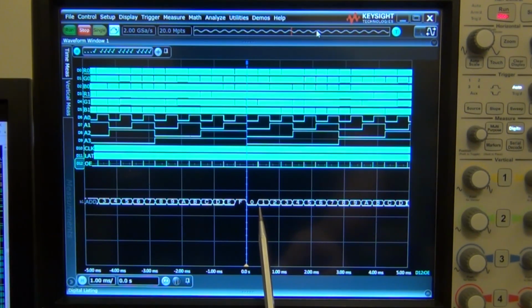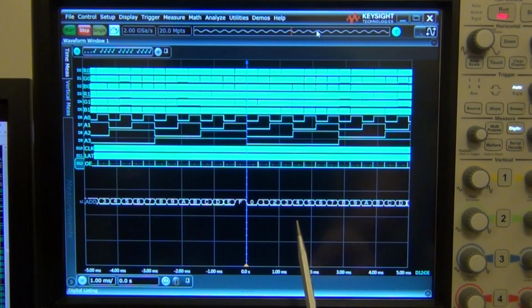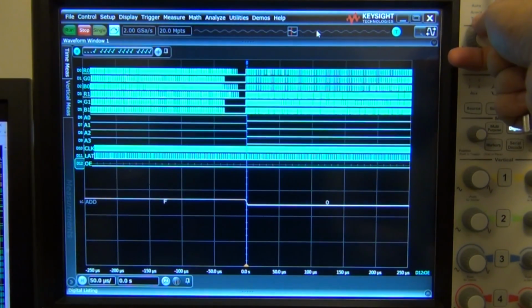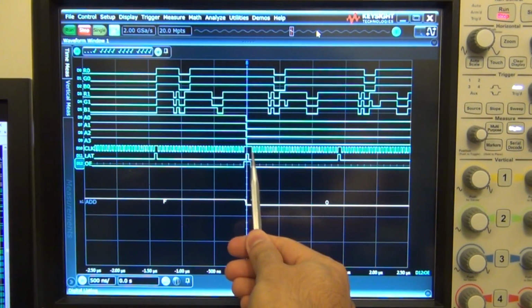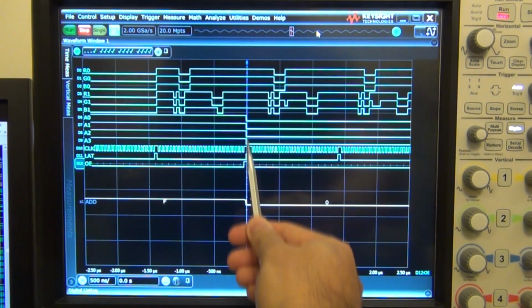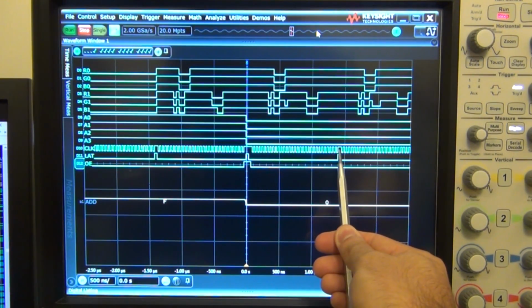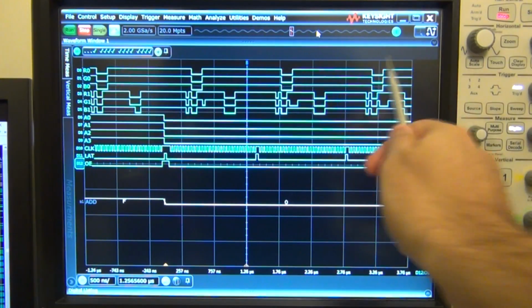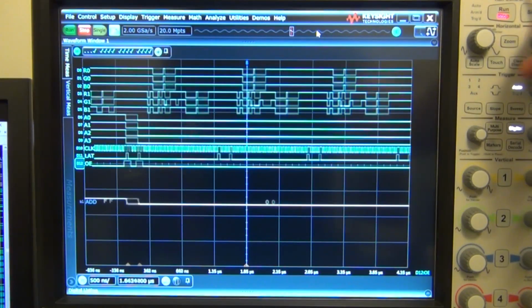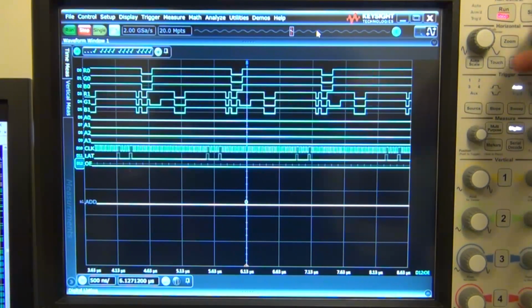and of course a whole lot is happening between each of the lines. All the PWM, all the output enable latch lines, and all the output enable bits that are triggering, they're all happening within there. So if I go ahead and zoom in here, eventually if I zoom sufficiently in, you can see the clock frequency right there. So here's the address changing, here's the clock frequency, 32 clock writing 32 pixels, another 32 clock writing another 32 pixels, and you can see all the data, the PWM data happening on the right.